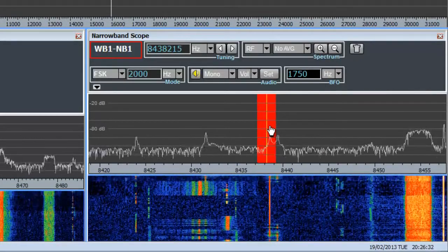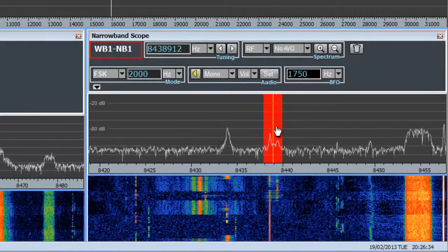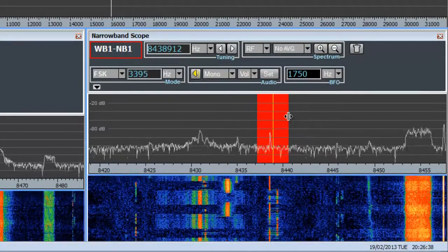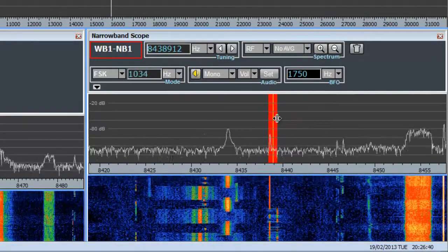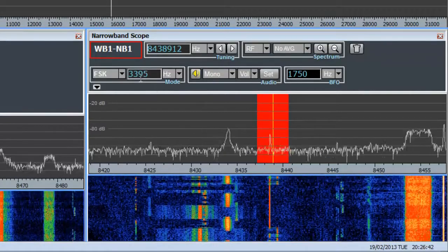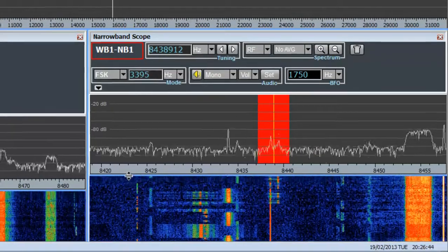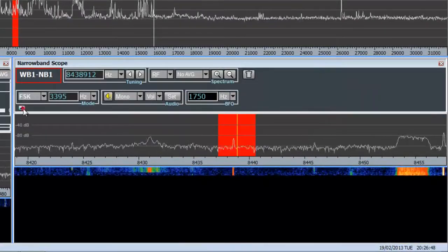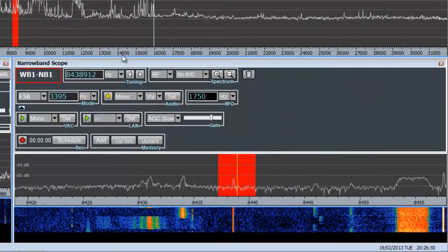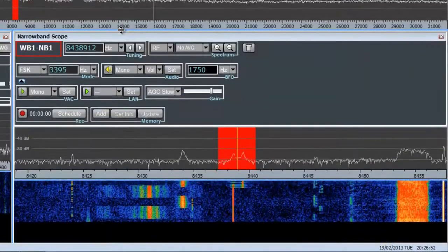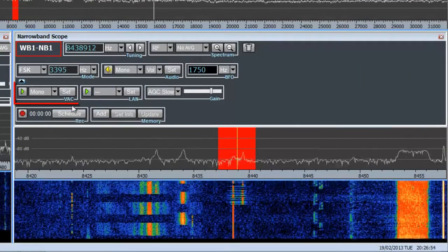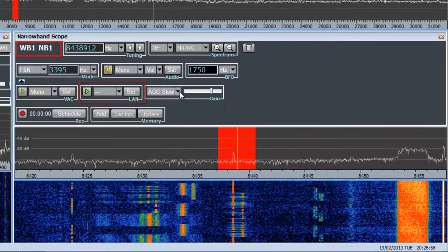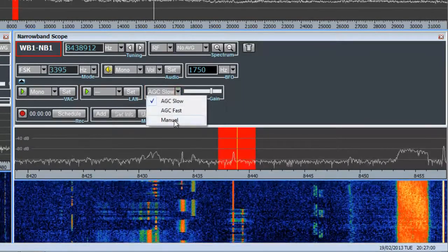Channel bandwidth can be modified by selecting and dragging the shaded area edges, or by editing the frequency directly. In order to stream demodulated audio towards external software decoders, click the expansion button. Streaming can be by virtual audio cable or by LAN. Gain can be manual or automatic.